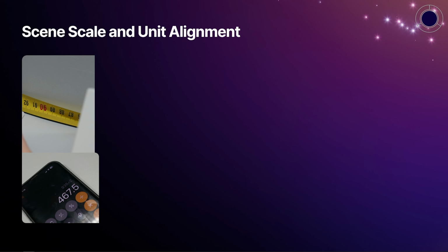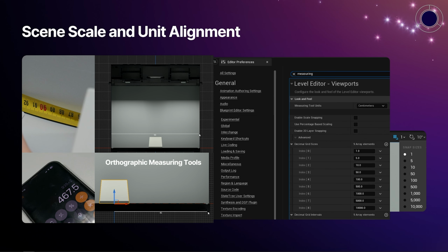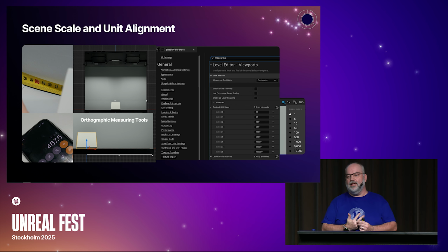And then once you have those measurements, Unreal becomes super easy because if you go into any orthographic viewport and middle click, you get a measuring tape and they're in real units. So you can go in and set centimeters or inches or whatever crazy unit that you want to work in right inside Unreal. It's as precise as a CAD software that way.